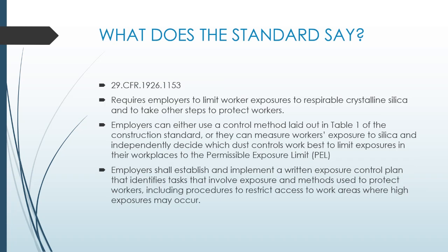So what does the standard say? Remember the 1926.1153. The standard says we have to limit your exposure. We want to make sure you're not being overly exposed or exposed to levels above the action level or the permissible exposure limit. It gives us two options. We can use Table 1, which we'll look at in a few slides, or the alternative exposure methods.